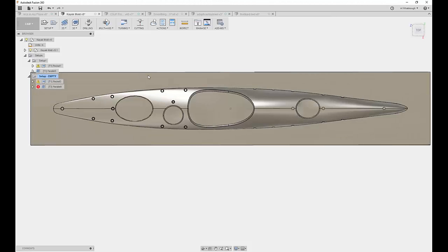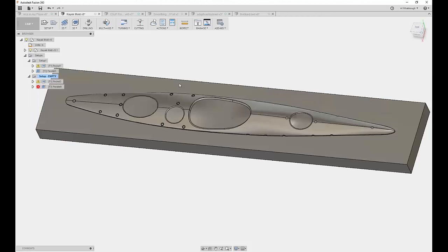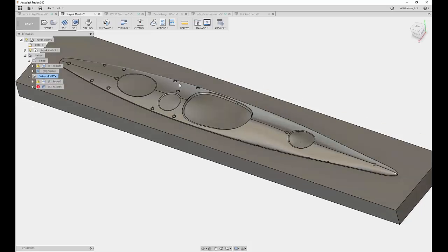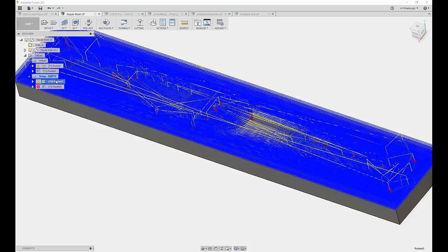Anything that I missed, things that you think people should know about how we calculate and what can make things calculate faster? Not so much about the toolpaths calculation, but regarding the stock simulation, we have these two major modes, the 3D fast mode and the standard mode. And we don't really have one good stock simulation that can be used in all different cases. Each individual mode comes with its own limitations and advantages.